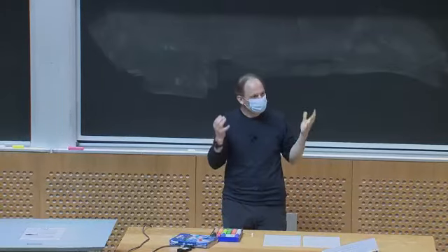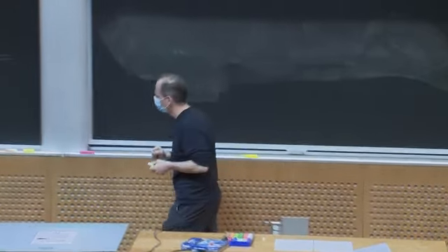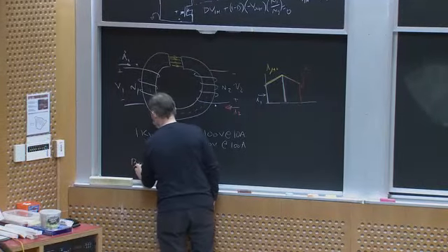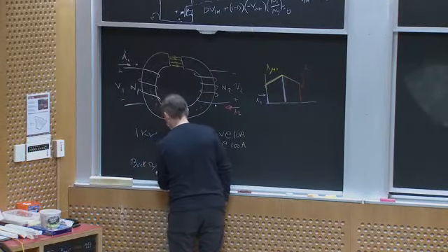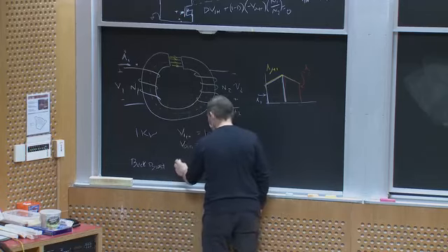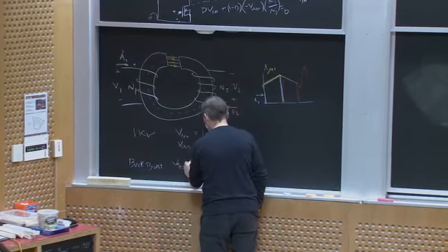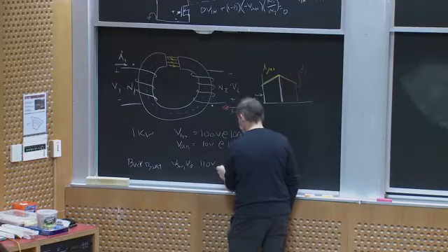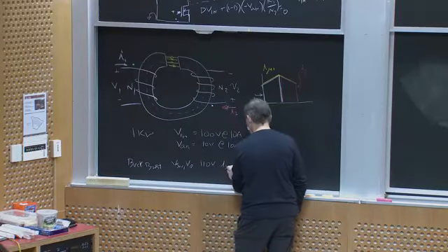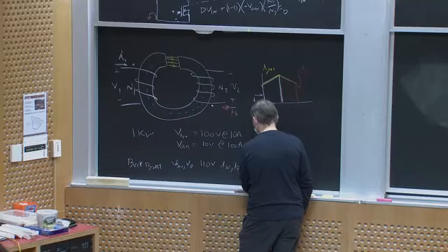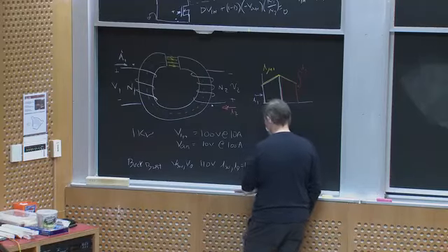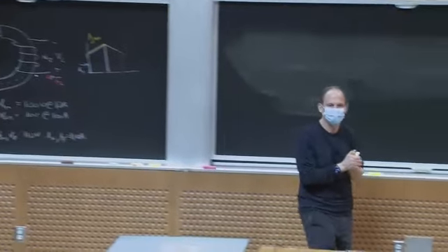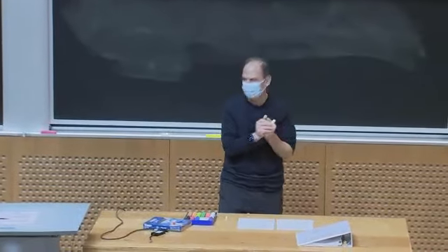What would it look like? What would the stress on the switch look like? Well, for a buck boost, what I'd end up with is V switch and V diode being 110 volts, and I switch and I diode would be 110 amps, right? So that's sort of more than 10 kVA of switch rating there and diode rating, okay?